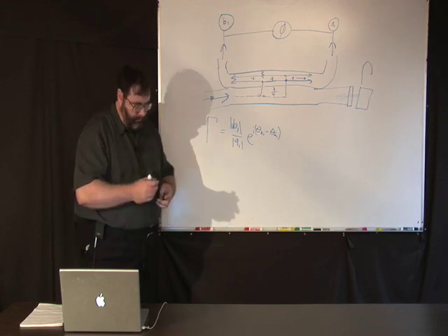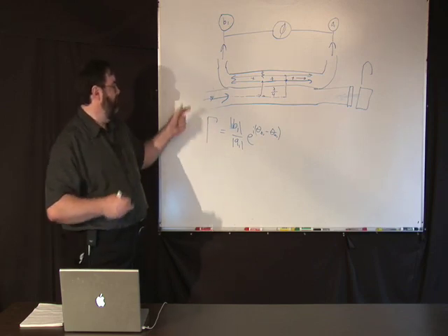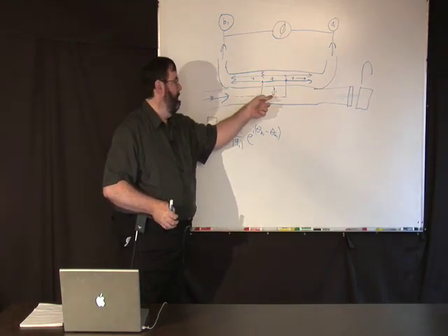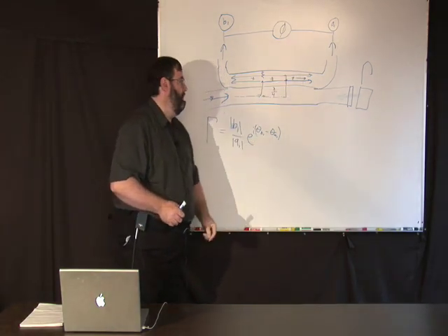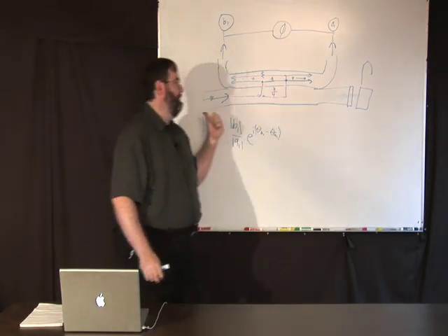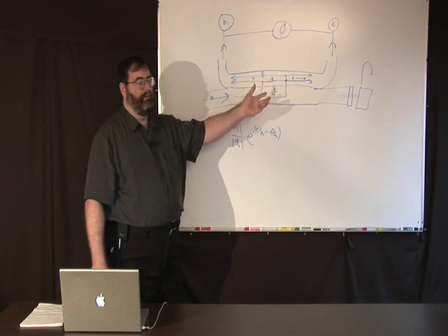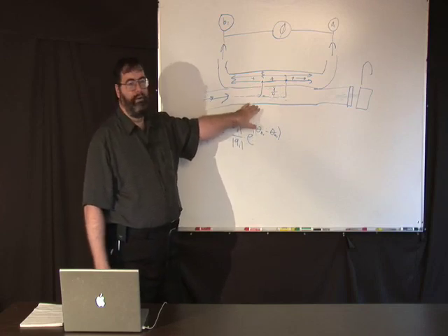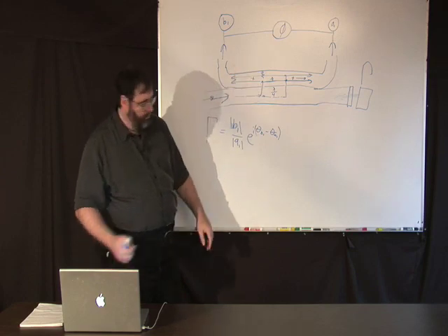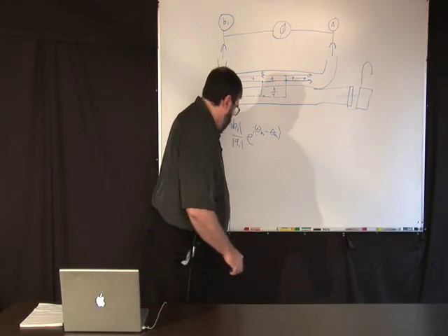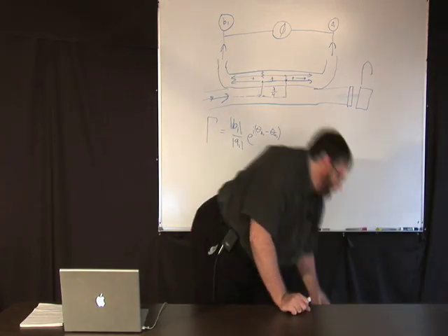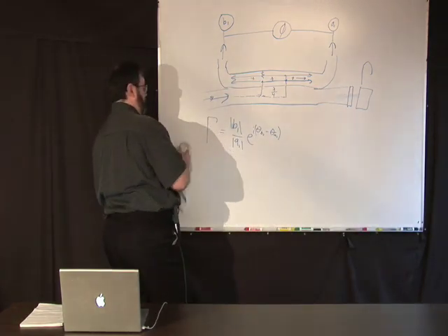What you really have is, this is not going to be exactly lambda over 4, so there's going to be some signal going that direction. There's going to be some signal reflected back here, even if you had a perfect load, because this is going to be imperfect. So we don't have a perfect test setup. Well, what do we have? Well, you could model this reflectometer using S parameters.